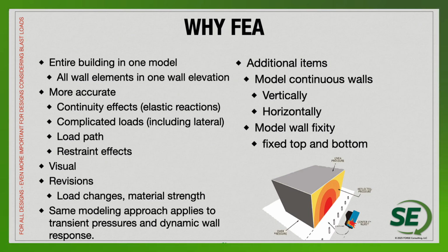So we have a better understanding of continuity and complicated load path and restraint effects. Maybe for this wall we want to consider fixed bases, fixed at the floor lines, the continuity that you would have if it's a multi-story type of design. So making sure that we understand all the different aspects of how that force is going to move through the building and be shared to the different masonry wall elements.